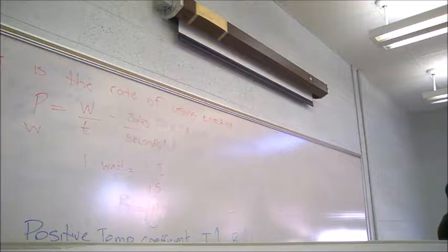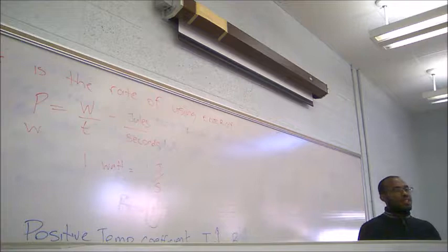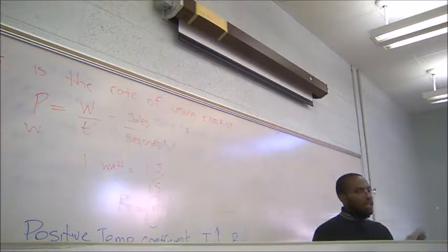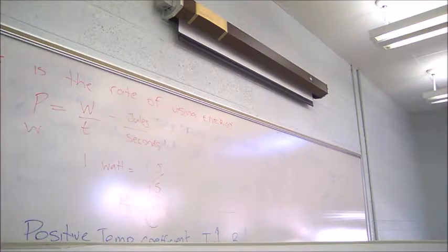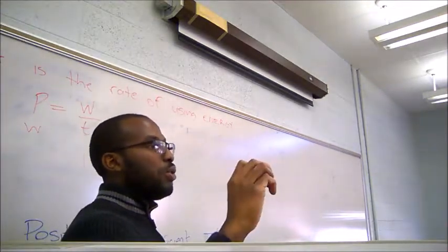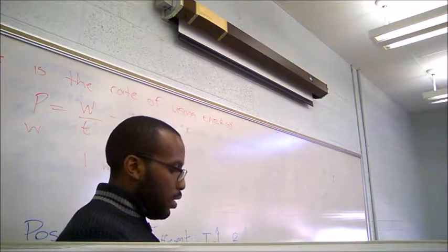Now I want to come to resistor color codes. We said the resistors are manufactured to have a certain resistance. In the case of the big resistors, it is written on them. For example, this one says 10 watts, 100 ohms, and 5%. So all the information you need is on there already. It tells you the wattage, the resistance, and the tolerance of the resistor. We're going to talk about tolerance now.